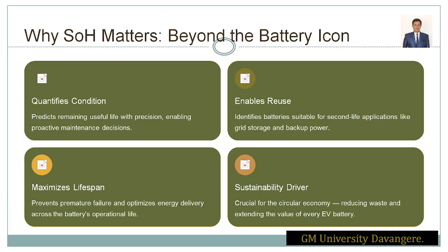One best example you can see is the Tata Nexon, right? The Tata Nexon is one of the best examples, where you can take the EV pack at 75% SOH. You can calculate it for 75% SOH if the rating is 30 kWh. When you multiply by 0.75, what is the life actually left over out of 30 kWh? The life is around 22.5 kWh. That is called the RUL, the remaining useful life of the battery, right?